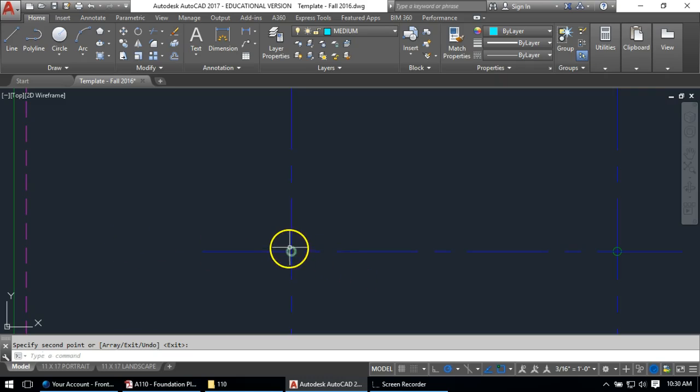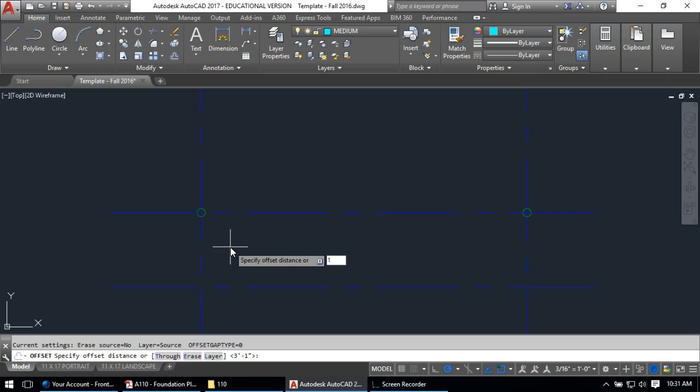The stairs are going to start 3 feet 1 from the center line of this column. So since this is a center line, I'll just start by offsetting that 3 foot 1 down. And the stairs themselves are going to be 3 feet. The railing centers are 3, 4.5, and of course the railing is 4.5, as we can see in the dimensions, and the railing center point is 1 3/4 from the center point of this line. So I'm going to have to start there. I'm going to offset 1 3/4 of an inch.